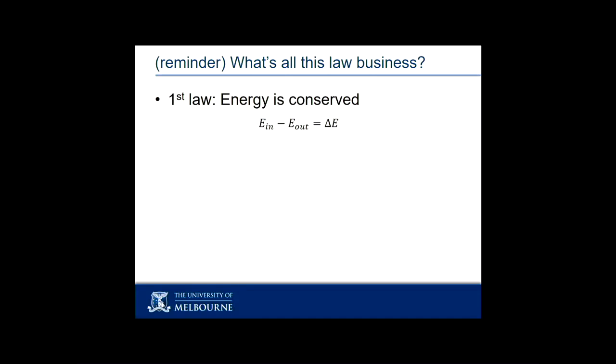That looks pretty simple. It means there must be a concept of how do I measure the energy of a system, which is kind of what we do here. So we need a number, we need a unit, and we need a number to represent the energy. Temperature is not that number. Temperature doesn't have a unit of joules. We measure energy in joules. Temperature gives us an indication, a guide for the thermal energy content of something, but we miss the energy content due to pressure. We miss any nuclear energy content. We miss any chemical energy content.